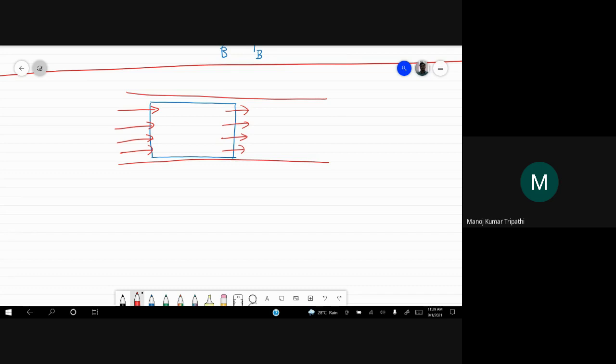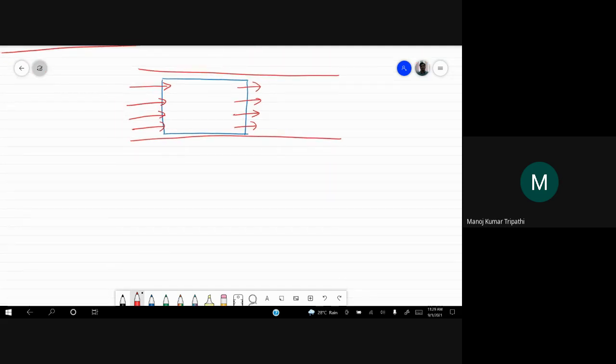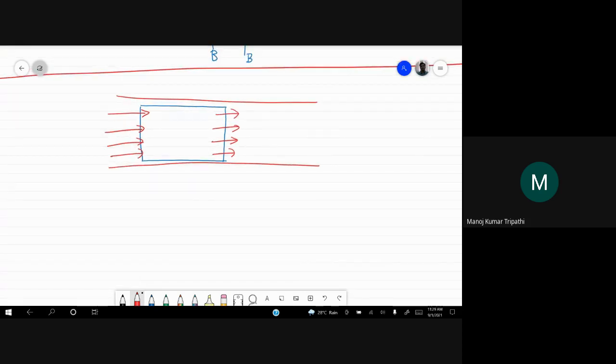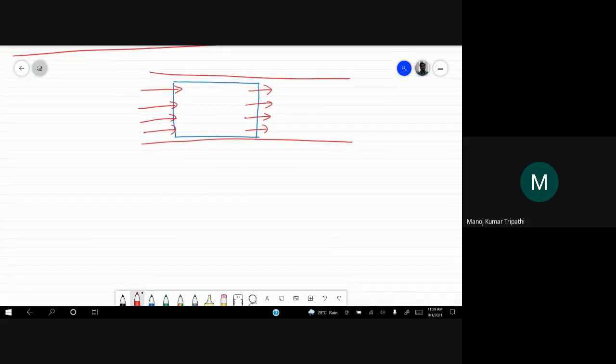And how it simplifies the problem is that we will have to take care of the forces acting only on this box always. The force can be changing in magnitude and direction on the boundaries of this box, but the boundaries remain fixed. So this simplifies our problem. We don't have to change the boundary every time. So this is also known as control volume analysis.